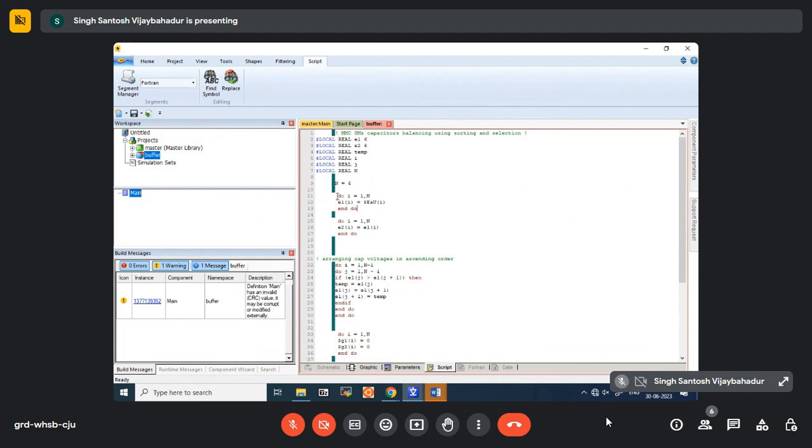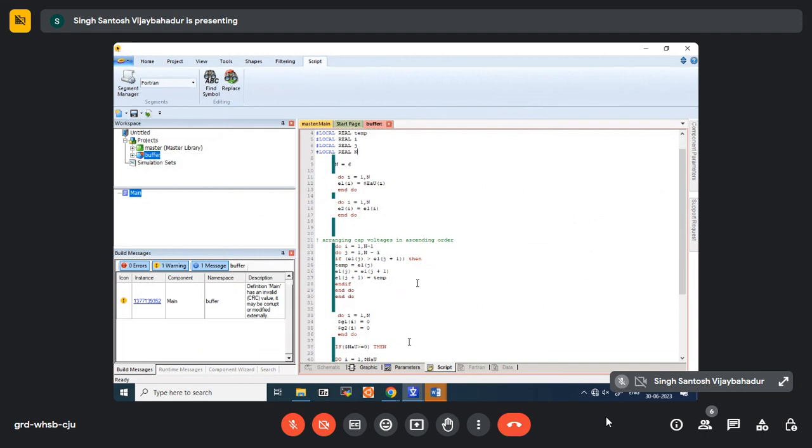So that is the loop. I have defined these variables left of that green line, and all the code is right of that green line. It is preferable, not a hard and fast rule, to write it there, from PSCAD people. There may be some error that is not showing here; maybe some line gets missed during compiling. So it is preferable to write the code in the right half, right of that green line.